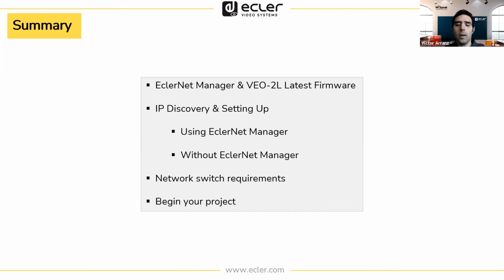We can go directly plugging it into a TV and looking to the bottom corner, the information that appears there. We can access the web interface also, and finally, we can do it through serial port connection and asking directly through an RS-232 command which IP this device has.